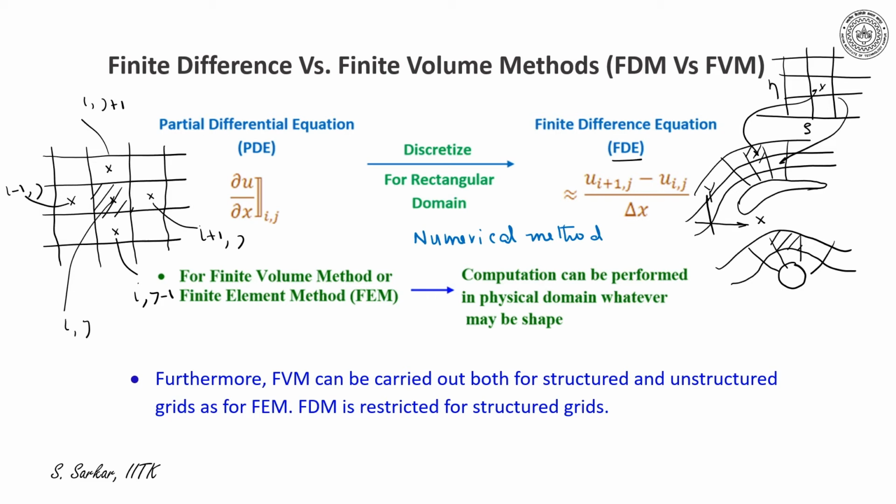Thereby, you appreciate here that using finite difference method for solving flow through a body, where the surface is curved, not rectangular, will have to go through some additional routes: transforming the governing equation to the computational plane, solving those equations in the computational plane, and then transforming the variable back to the physical plane to get the flow field.